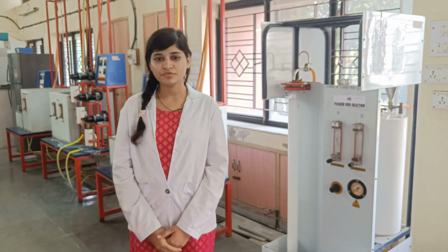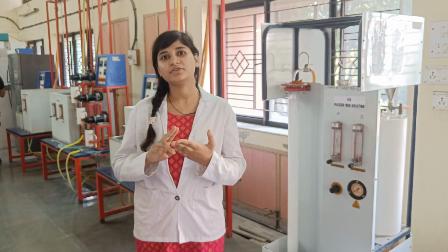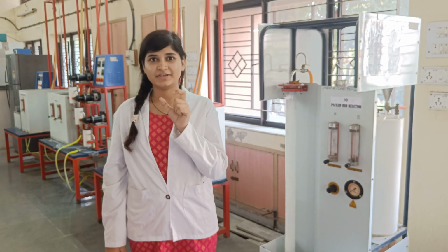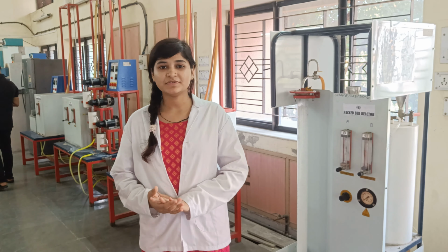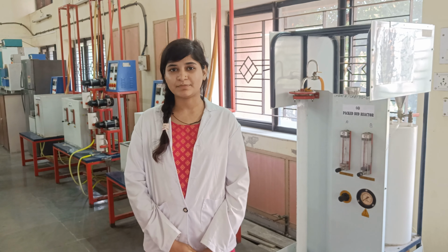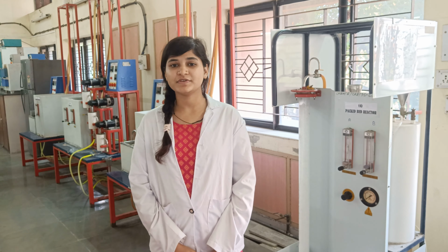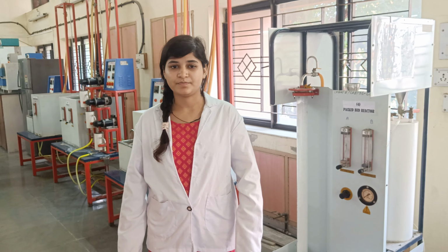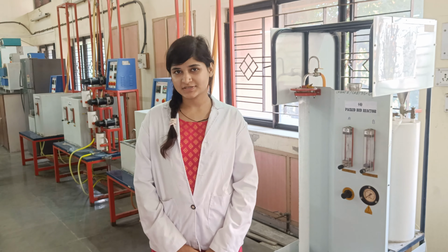In the earlier part of the video, we have seen theory, procedure, calculation, and found out the rate constant K. Now we will see the advantages and disadvantages of packed bed reactors for saponification reactions. Packed bed reactors can be a suitable choice for saponification reaction, which typically involves the hydrolysis of esters in the presence of alkali to produce soap and glycerol. However, their effectiveness depends on the specific processing.